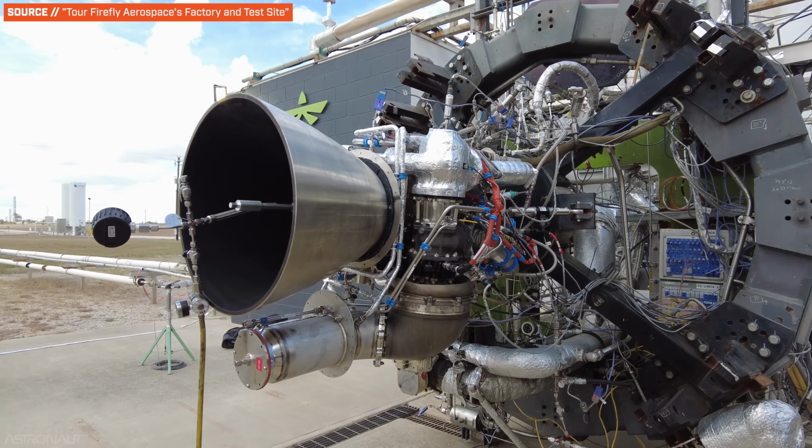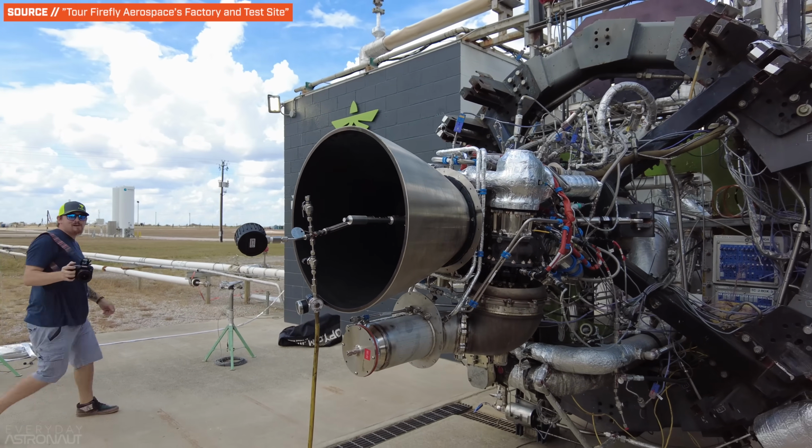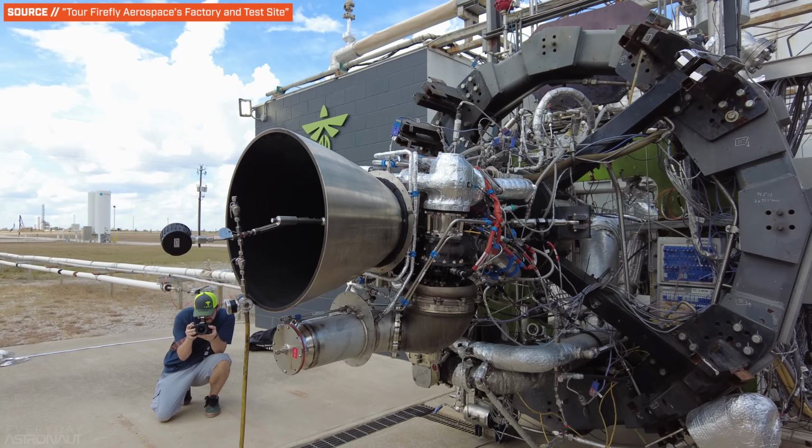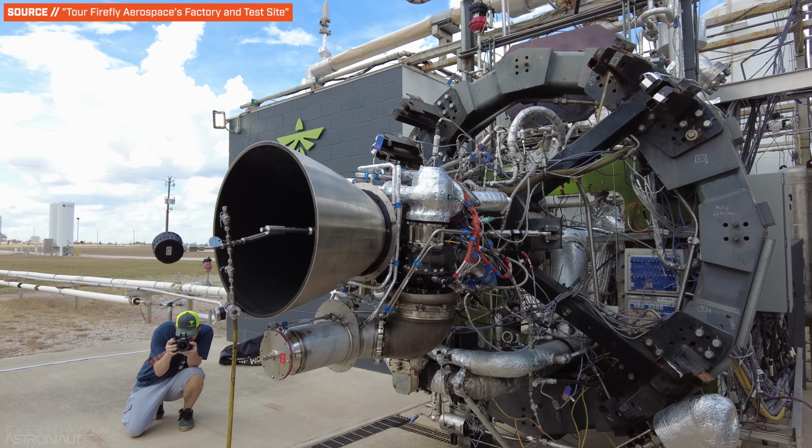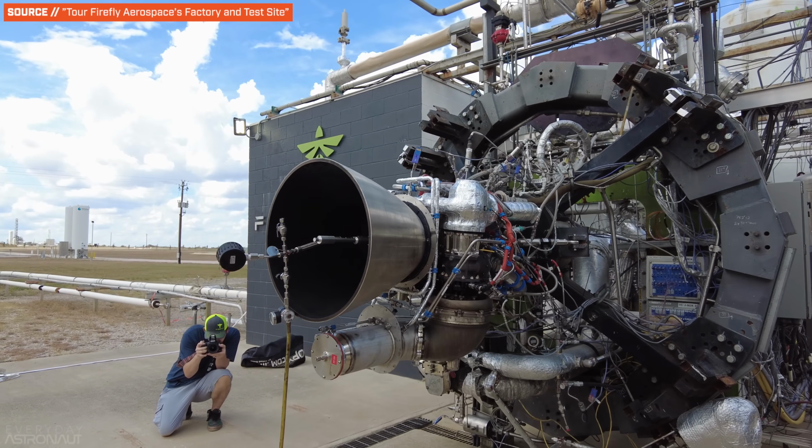Okay, so hear me out. What if we just punched a hole in the side of the combustion chamber and just took that high pressure gas and used that to spin the turbines to run the pumps? Now there's an idea. This is essentially what the tap-off cycle or combustion tap-off cycle is. You can remove the complication and weight of having a preburner or gas generator and just use the main combustion pressure. You only lose a little bit of performance by having basically punched a hole in your engine, but you free up a lot of complexity for sure.